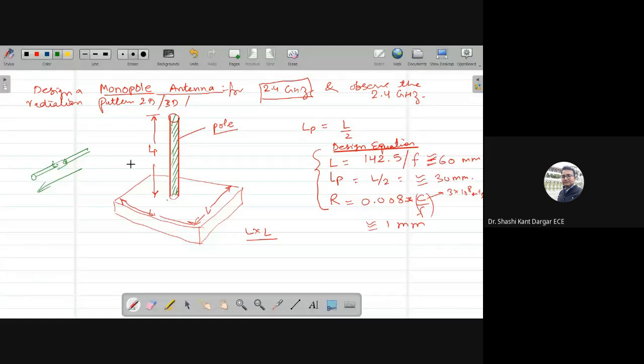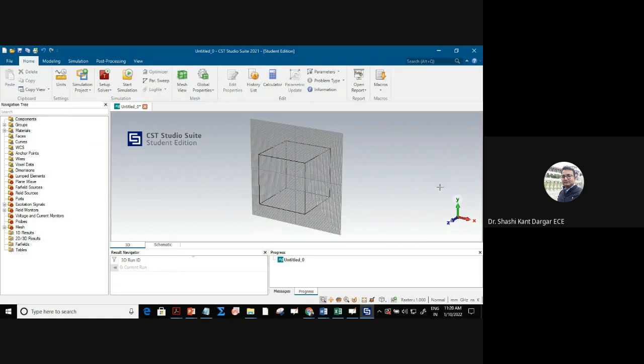But now I am designing an antenna for this case, and I need to do it in this direction. So let me say it is the y direction. Let me see what coordinates are shown. Control H. You can see the coordinates here on the right side of the screen. Y is upside, X and Z are the directions of the cube like this. This is X.